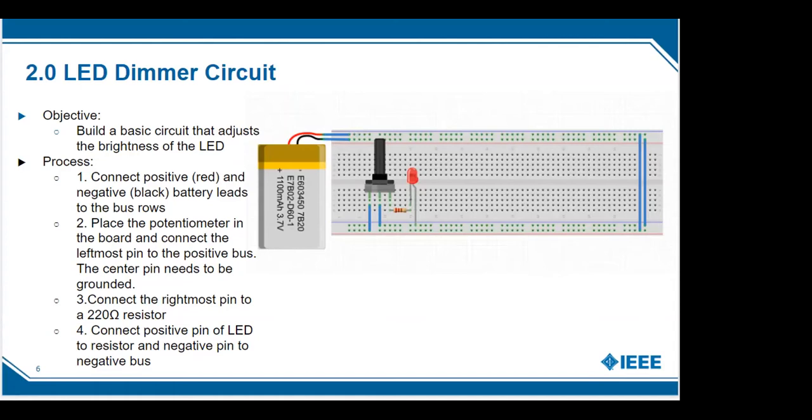And then since I made this circuit go all the way across the breadboard, what I then did was I used 2 jumper cables over here to connect the other 2 bus rows. And then I did this just for perspective, so you can see it better, because this potentiometer kind of gets in the way of all the connections there, so that's why I jumped it across.